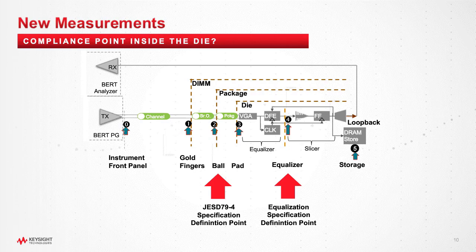It really wasn't possible to, say, attach a scope or a bit error rate tester and calibrate all of that to have a known signal at the ball of the receiver package based on having an open eye, because the eye there would be closed. The only place that there would actually be an open eye that you could write a reasonable spec against was inside the die after the equalizers. But that's not a physically accessible point.